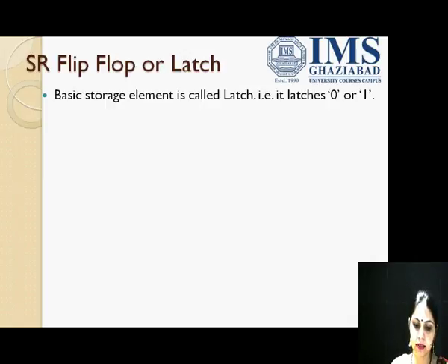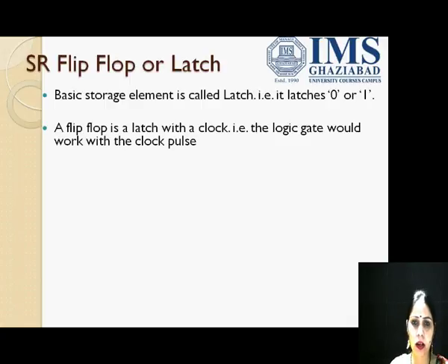0 means we have latched the door and 1 means it is open. A flip-flop is a latch with a clock basically. That is, logic gate would work with the clock pulse. Say we are designing SR latch, we would not be using any clock. And if we were designing a flip-flop, we would be adding a clock to it, and our inputs would be working on the clock pulses only.